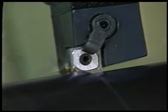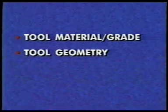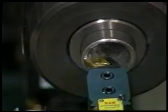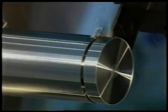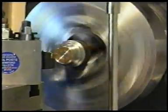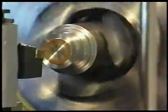Several decisions are required when choosing tools for turning, including the selection of the material or grade, the geometry, and the tool holder design. Just a few basic geometries and carbide grades are used in 75% of turning applications. Tooling decisions for lathe operations, such as hole making, boring, threading, and parting off, require unique selections of grade, geometry, and tool holder. When turning with inserts, much of the required geometry, such as clearance angles, is built into the tool holder rather than the insert itself.